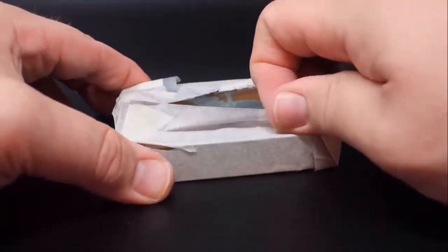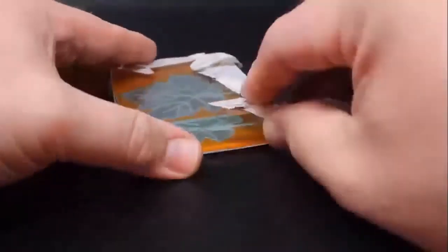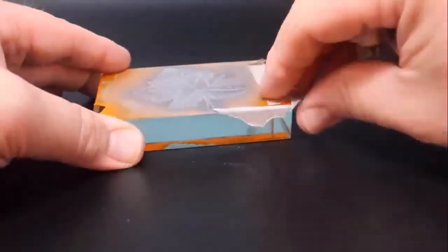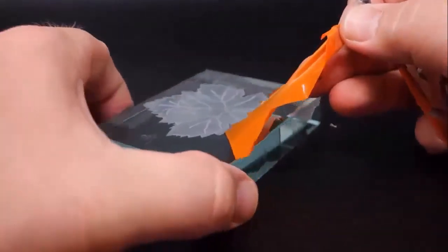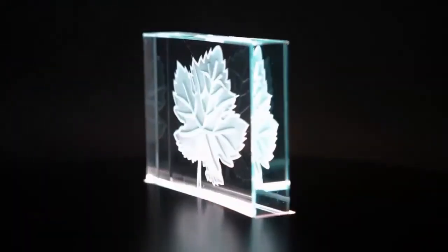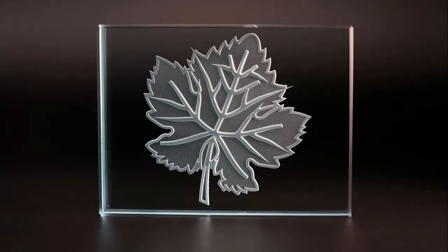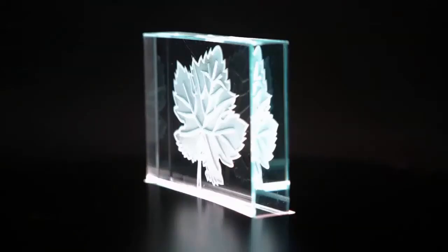That's the effect you can get with sand carving by lowering your air pressure down to like 5 psi, keeping your distance the same as you did on the white veins in the leaf. And just by going to a lower pressure, you're able to get a gray image instead of a pure white image. So that's the effect of a 2-stage. Very awesome. And it just sticks out in your showroom, sticks out online, as you can see in this run through.